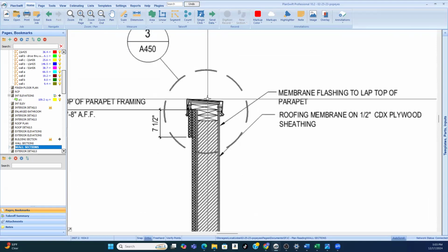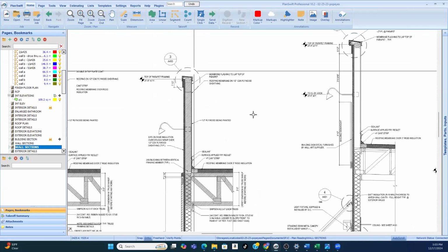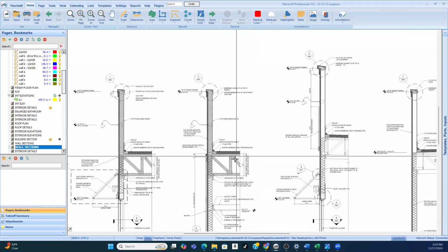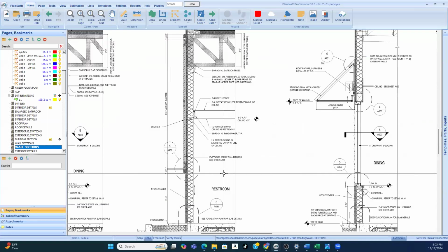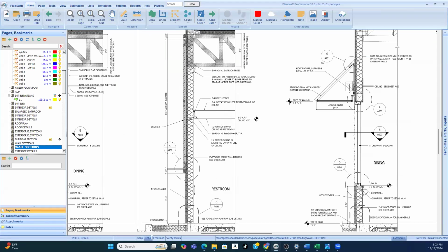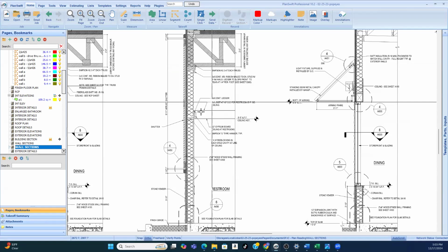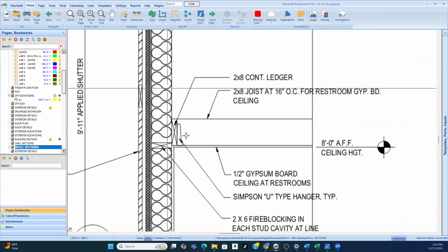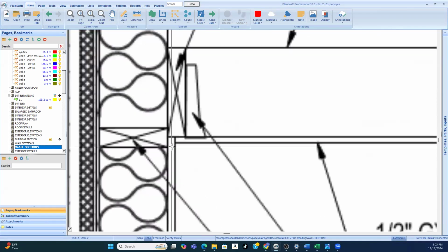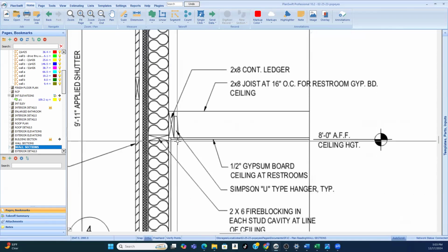So we have plan view, the most basic of the views. Section view gets a little deeper. Think in terms of our framer now. Now we not only know how many linear feet of each wall, we can determine the height of the wall too. We can determine the drywall height. We don't have drywall all the way up as far as the stud, so we want to make sure we have that.